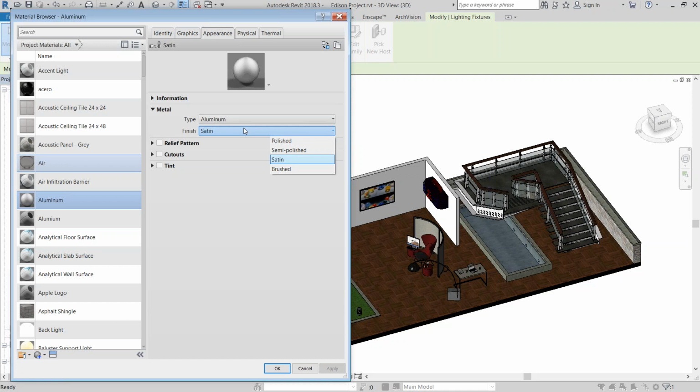If you look at your Revit template for your company, which has probably evolved from the Revit template from Revit, you'll notice that it's full of procedural materials. And if you look at steel as a material, they're using a type that's stainless steel. So the first thing you're going to see in your project is you open it up, you start to walk around in Enscape, you turn off the walls, and you're looking at the mechanical system, and all of your structure looks like it's been dipped in chrome and polished, and that is incredibly unnatural.